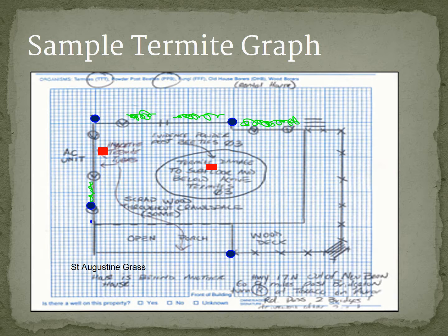As a matter of fact, a lot of you have probably heard of crawl space encapsulations now, which has even become code in a lot of cities and even counties, because really you don't want that moisture to ever get in the crawl space. But even if it does, you at least have to have a good vapor barrier on the ground and a good venting system to help keep that moisture from building up.